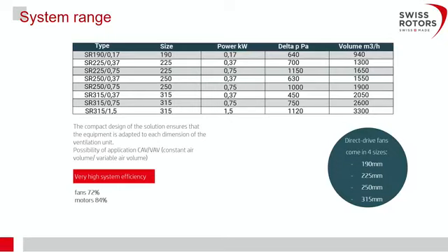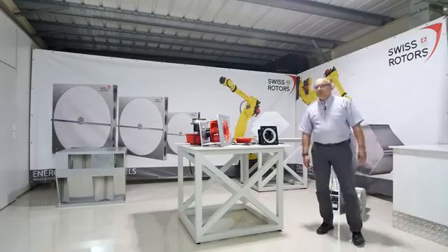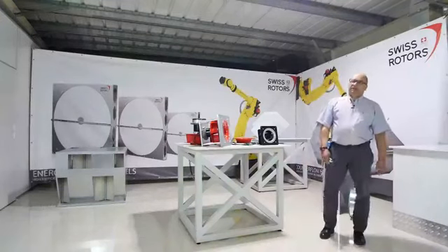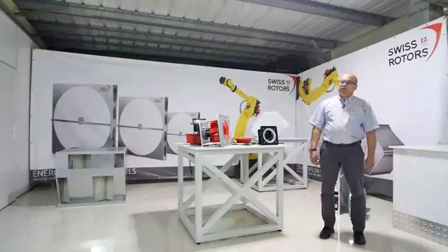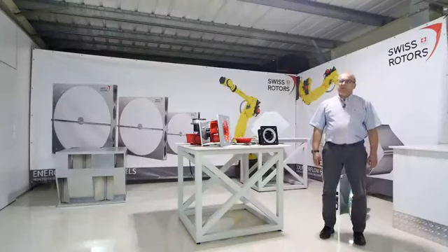And of course, thanks to this controller, you can actively check the air volume and modulate it. It could be constant air volume, so if the filter becomes dirty, you can slightly increase the RPM to get the higher pressure and keep the same air volume. And also, for a different application, if you need a variable air volume, you can also modulate it and change the speed.